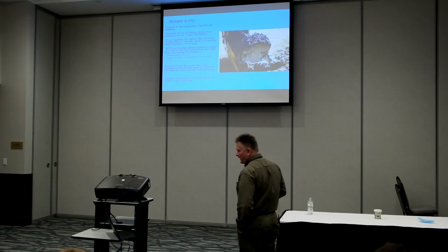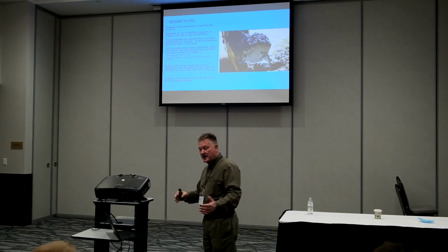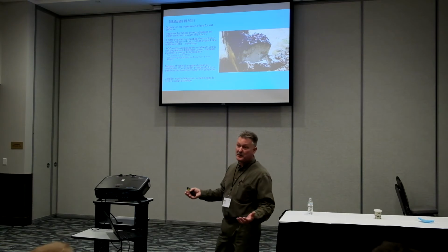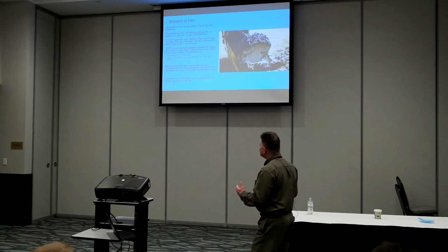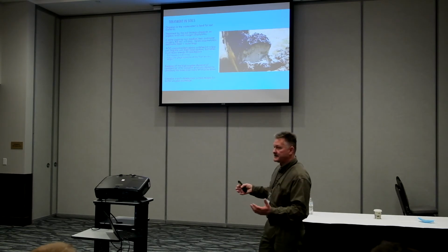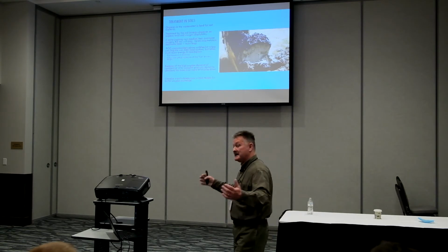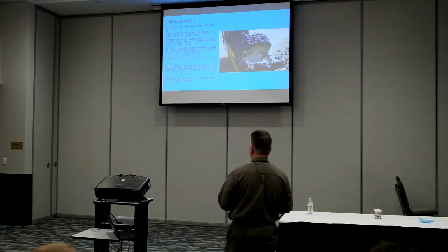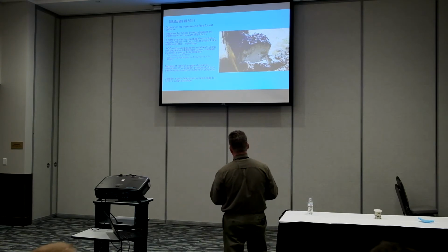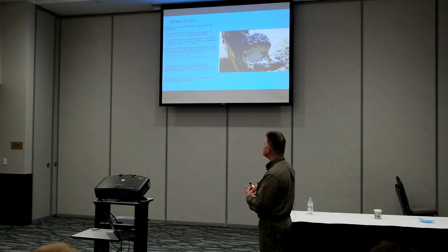So treatment in soil, you have to understand that the wastewater coming in is actually food for the bacteria. So treatment by the soil bacteria depends on how much food is coming in and the amount of oxygen that's coming in. Oxygen is critical for any kind of treatment to occur in the field or in a treatment system.